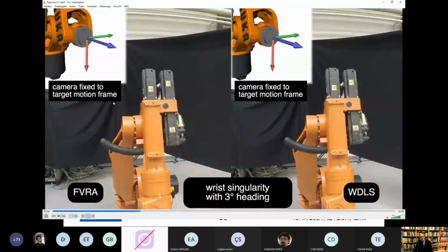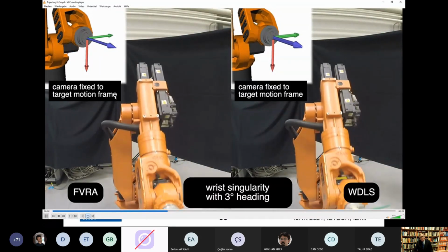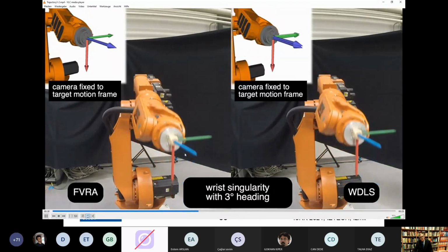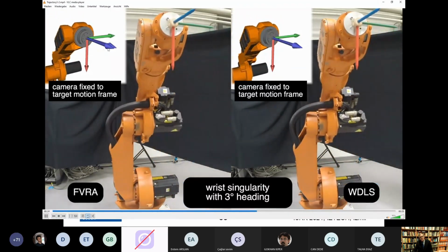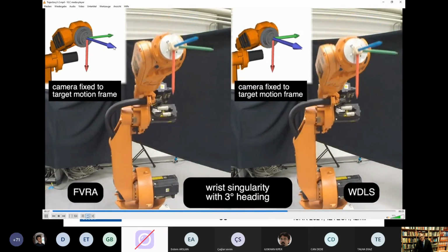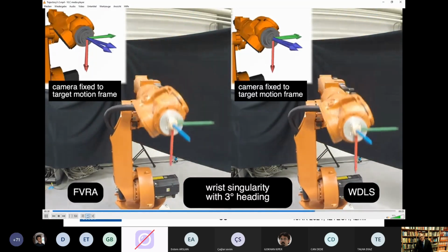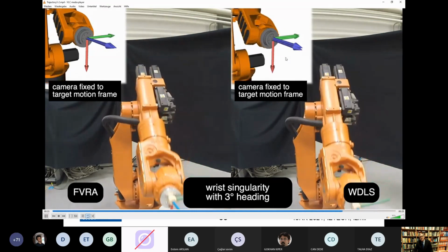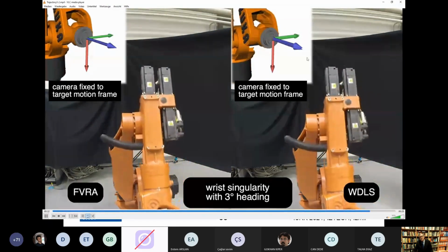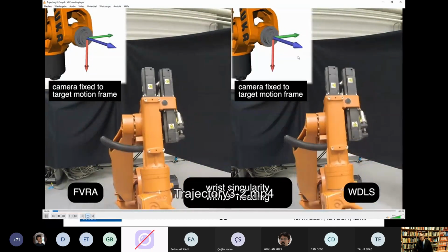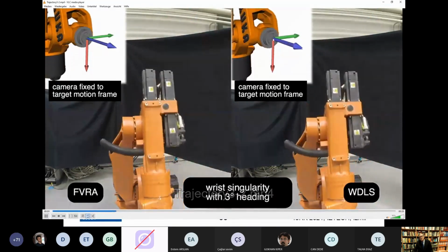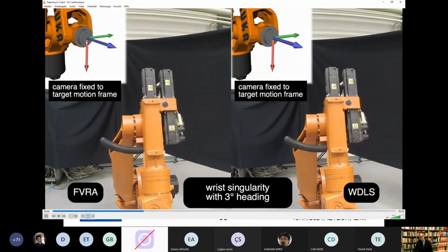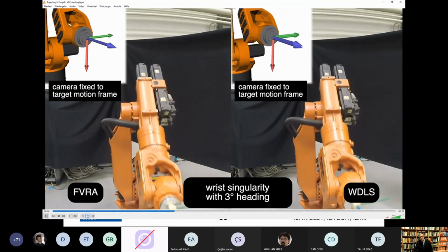And you see that if you use this virtual redundant axis, only when you pass through the singularity do you have an error in the direction of this locked motionless space. While if one uses the damped least squares method, first of all you spread it over the whole space. You see there was also a translation here, not just a rotation. Here you just have a rotation about this point.